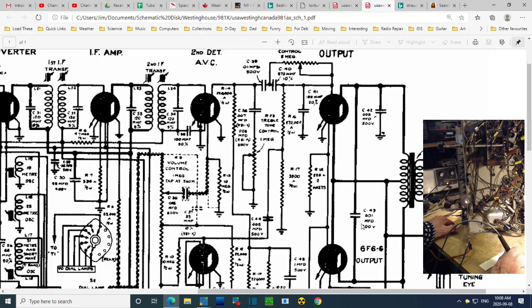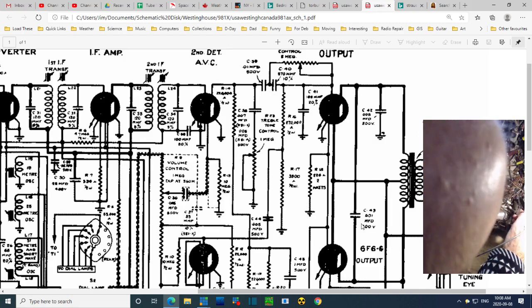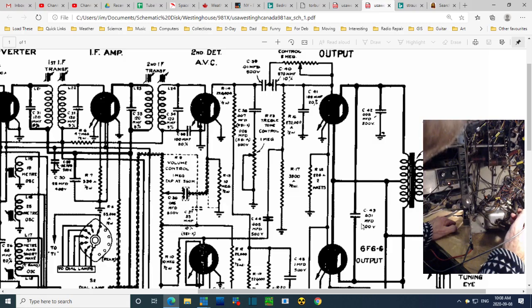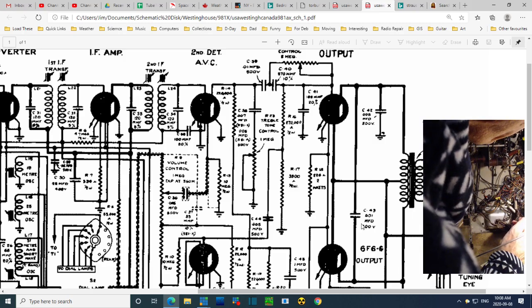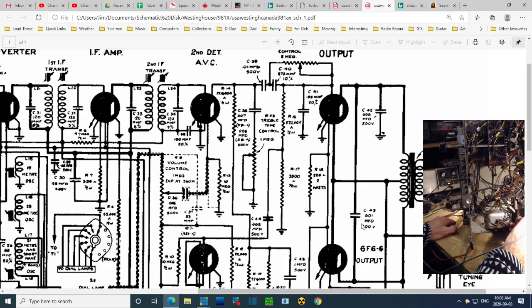Now, is the difference anything to worry about? What other voltages are not the same on these tubes? If we look at the screen, again, screen being higher, and it kind of has to be, 230, and the screen down here, 230 is exactly the same.